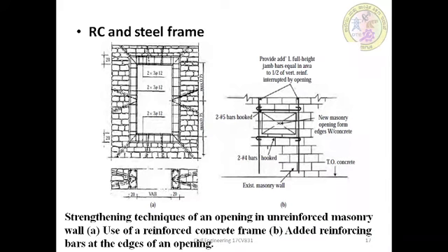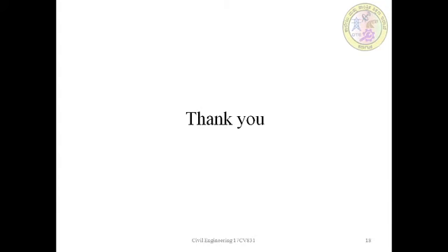This shows the complete procedure of how this strengthening technique for an opening in an unreinforced masonry wall is carried out, using the reinforced concrete frame and also adding reinforcement bars at the edges of the openings. So this is all about the different retrofitting techniques to be used for masonry buildings.